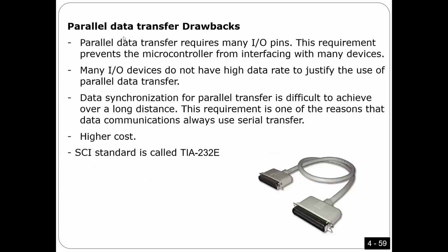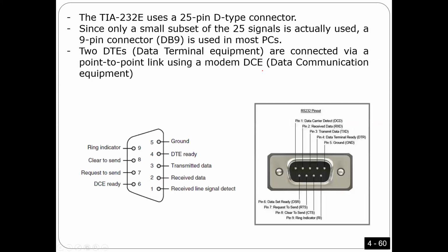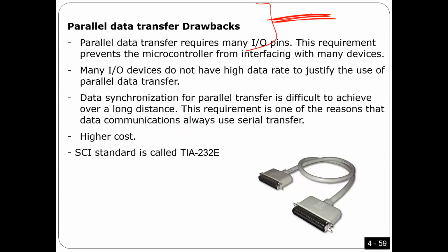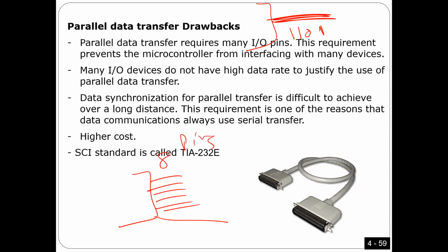Also, I want to talk about the fact that besides serial communication, we also have parallel data transfer communication. Usually for microcontrollers we don't use parallel, for several reasons. Number one, you know the idea of serial: you need only one pin, and then you send the data serially. Serial means 1, then 0, then 1, then 1, and so on. However, in the case of parallel, you need more than one wire. For example, it can be 8 pins, and you can output the byte at once. So I can put here 0, 1, 0 at once.